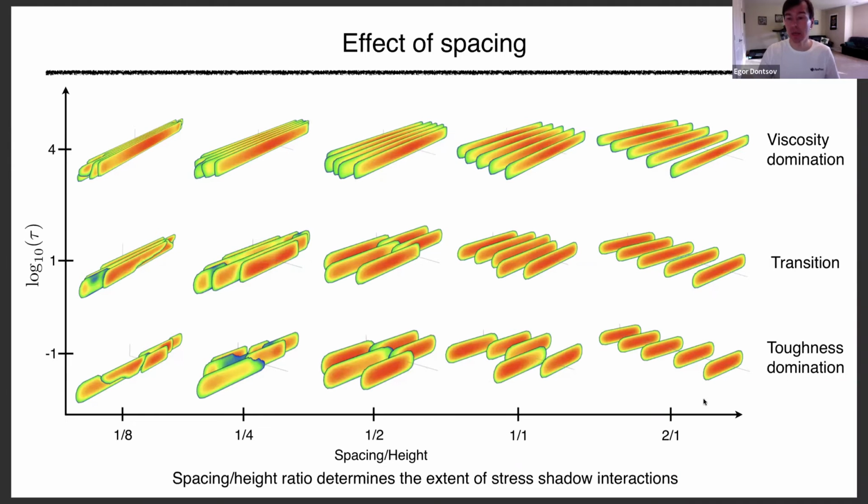And this is, by the way, if you try to run these things multiple times, or if you try to even add even more toughness, this is still the same. Or one reviewer asks for mesh dependence to see if you change the mesh, things are going to be the same. And again, they are qualitatively the same. Each individual fracture is a little bit different, but qualitatively they're very much the same. So the fractures really avoid each other when toughness dominates.